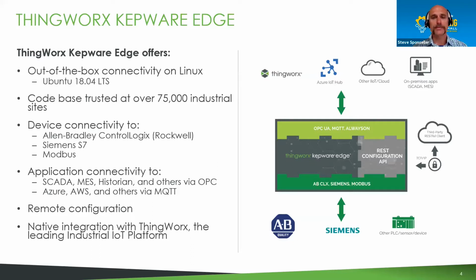It's the same code base as the Kepserver EX code base that has been used in many locations over many years, but with the Windows dependencies removed. In that it is a version 1.0, it's limited in its connectivity compared to Kepserver EX, but we'll eventually catch up. The very first release has our top 3 selling drivers, the ones that are used the most: the Allen Bradley ControlLogix driver, the Siemens S7 driver, and the Modbus Ethernet driver.